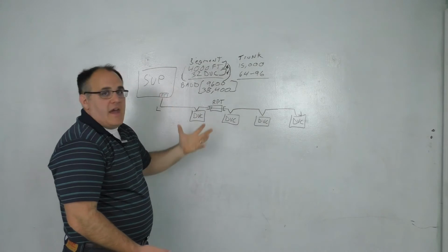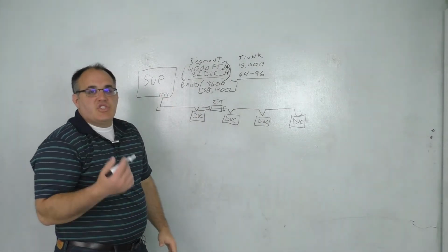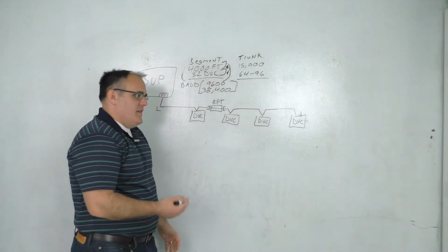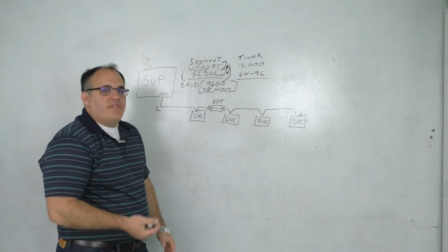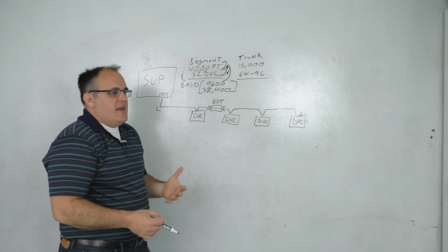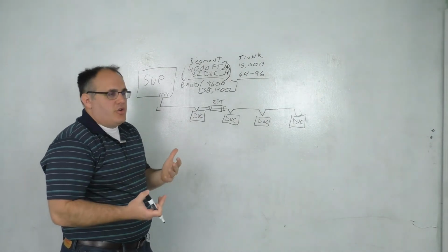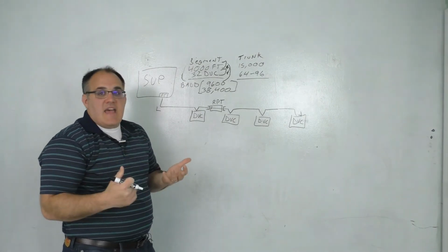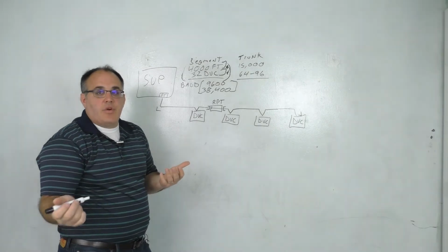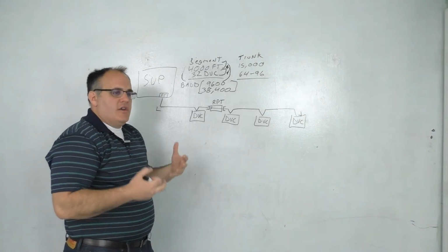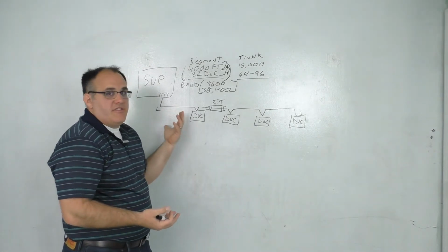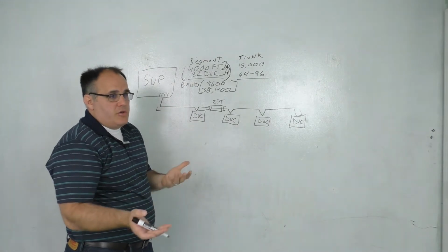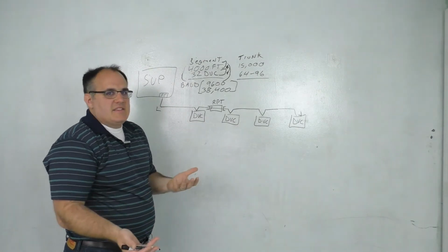So with that being said, with our segment length, our device count, and our baud rates all being clear now, we have enough information to start diving into addressing. Now, if you've watched any of our courses, or read any of our articles, you've probably heard of Ethernet MAC addresses. That's how you physically address the network interface card on your computers, on your supervisory devices that speak IP, on your controllers that speak IP, and it's a hexadecimal number.